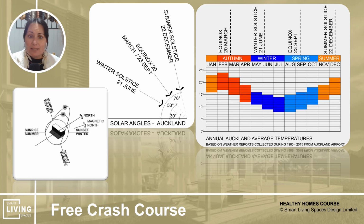So there are international standards called Passive House, and there are ways to improve these things. We just need to do the right things, not the commonly sold things and the commonly talked about things. So first of all, you need to stop that sun from reaching those particular windows, so you don't have to deal with the additional sun. Internal blinds are not going to help you. You need to stop that sun before it hits the outer pane of glass.